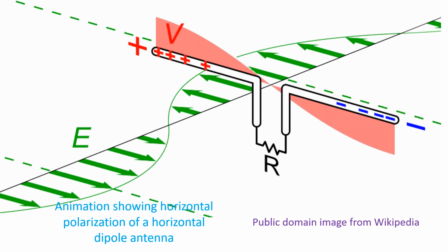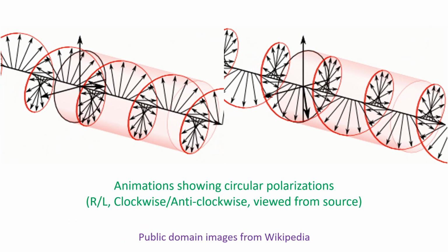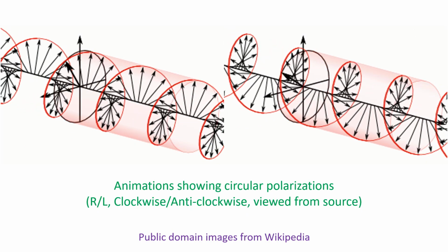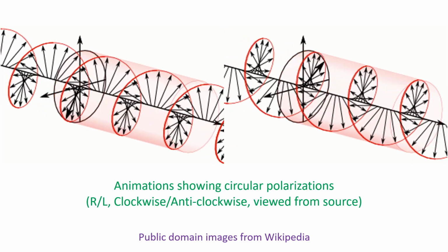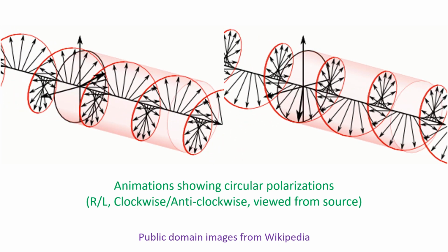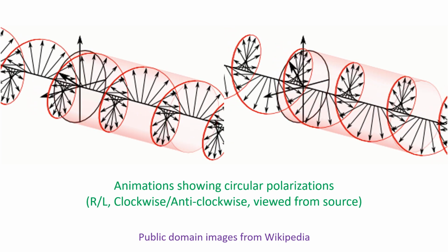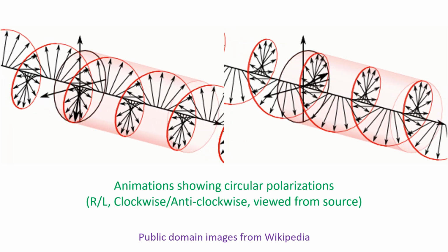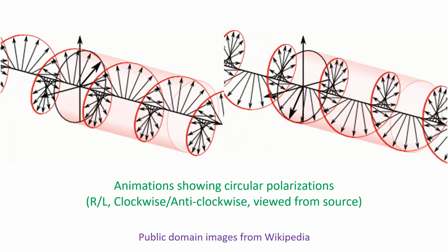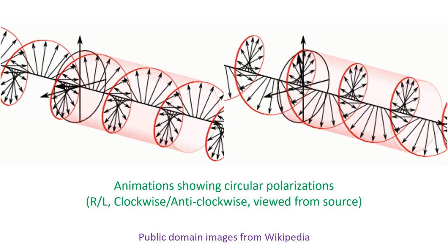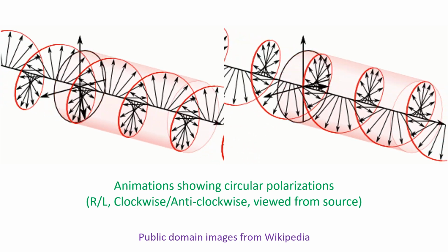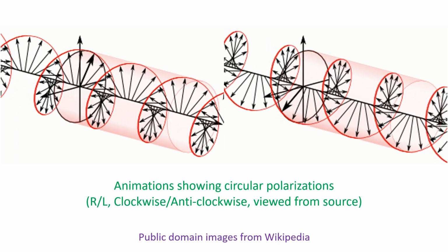which the beam rotates. Circular polarization is ideally needed for satellite communication ground station antennas. This is because the satellite spins and tumbles in orbit, so that antenna orientation changes continuously, though most satellite antennas have linear polarization.